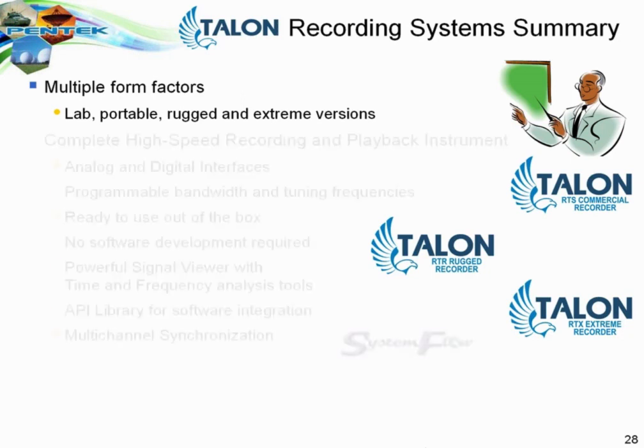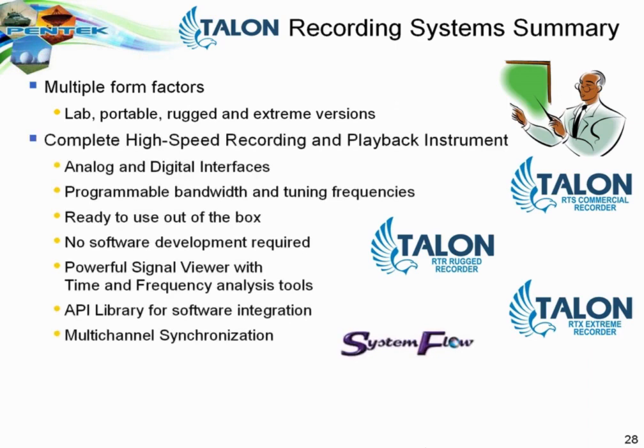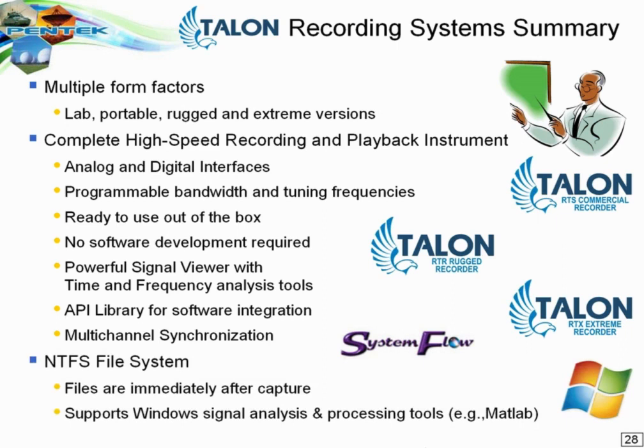And some of the RF products that we provide now, we have a series of products called Bandit, which you'll also be able to see on our website, where we actually have what we call slot receivers that exclude frequencies above and below a particular slot. And so if you had a high interfering signal that was in an adjacent slot, we would attenuate that sufficiently so that you could get the dynamic range you need to see the smaller signal. So I'm not sure if I answered the question directly, but those are my comments.